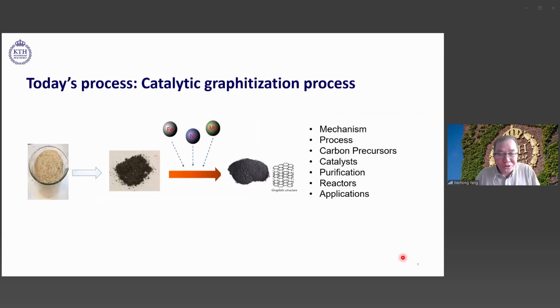We have biochar, we have biocarbon. We have this biochar from sawdust or agricultural wastes. In principle, it cannot convert to graphite directly. What we need is a catalyst. In principle, the catalyst is a kind of metal or metal alloy, for example nickel, iron, or molybdenum, and at high temperature you can get graphite.